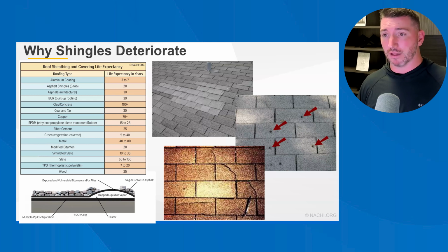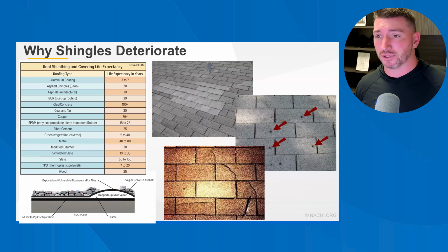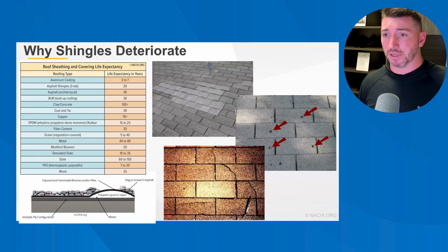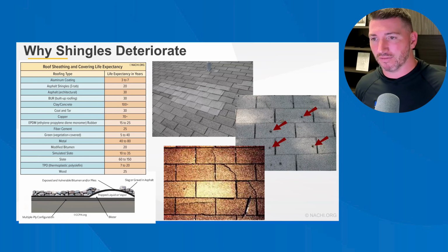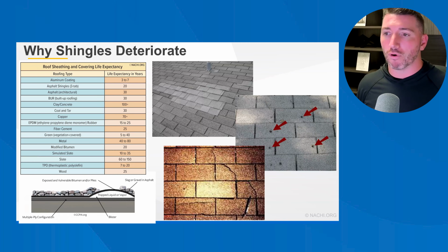So again, poor ventilation in a roofing system that builds up excess heat would certainly exacerbate that issue and cause those blisters to manifest themselves a little bit sooner than they otherwise would have. But even in a northern climate during a summer where the sun is just beating down on the asphalt, blisters will manifest themselves because of the manufacturing process, not because of the poor ventilation.